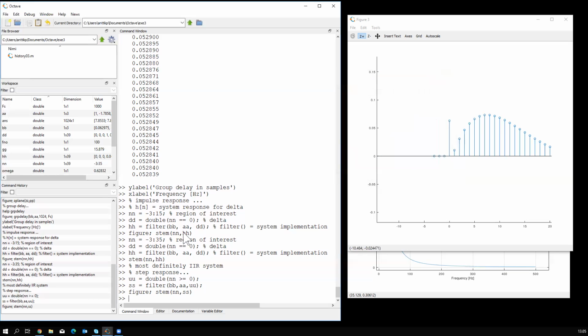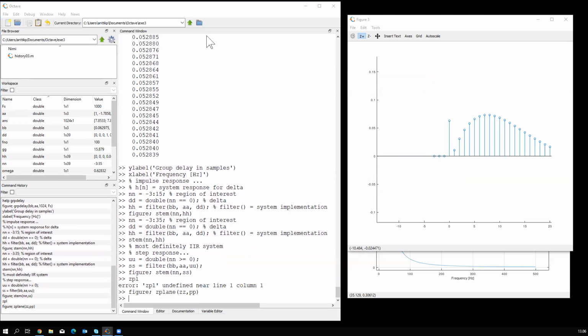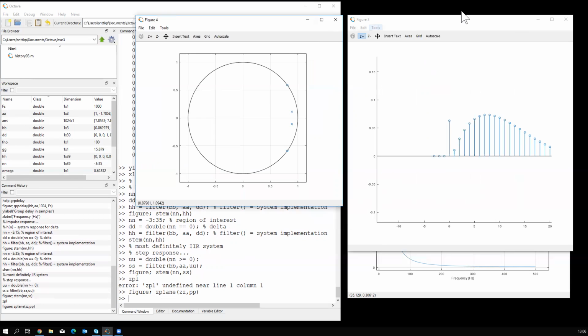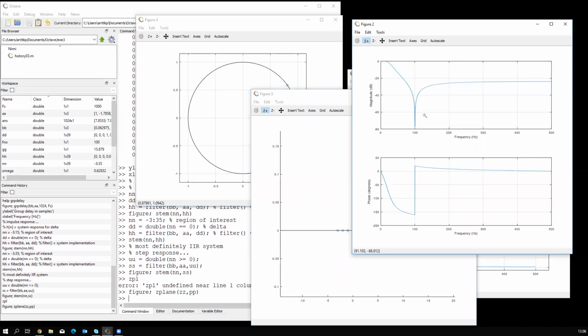So now we started from the zero-pole plane. Figure, Z-plane, zeros and poles. Started adjusting the poles to the right place. First, we selected the zero at 100 Hertz, then adjusted the passband gain, calculated the corresponding parameters, got the frequency response, calculated the maximum gain and scaled the system.